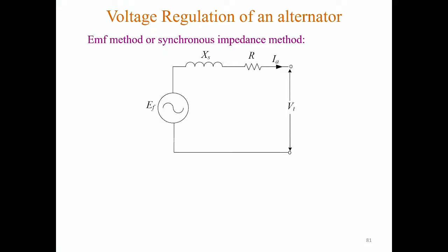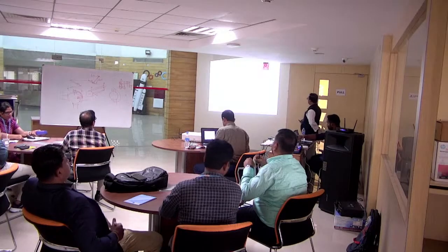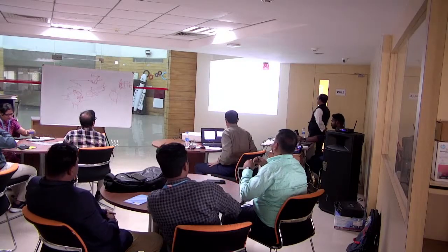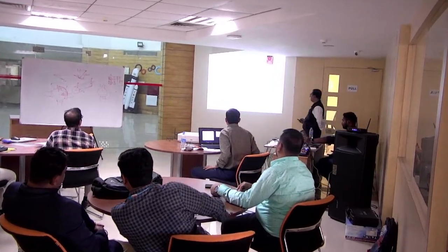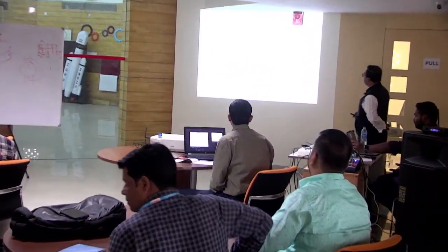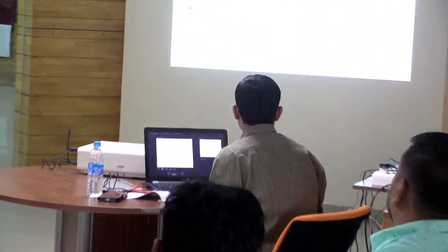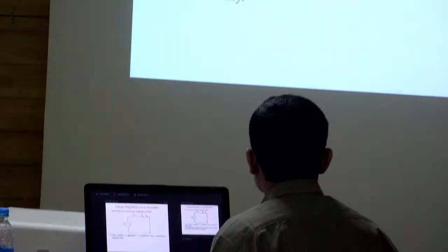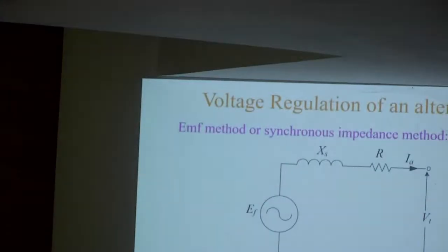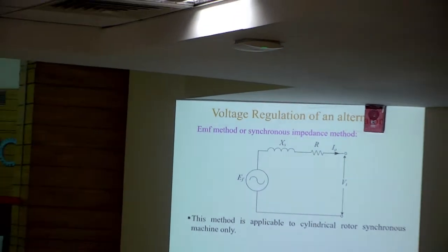This is the required circuit diagram. Here in this method we will use this OCC and SCC, and since this method is based on the calculation of synchronous impedance, this method is applicable to cylindrical rotor machine only,